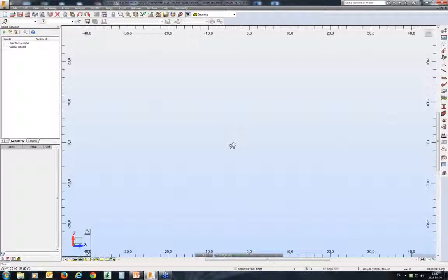Is there a method for fixing torsional stresses from the beam to the panel? Okay, there is a method. The surface elements that we have in Robot do not transfer torsion. So in this case, the solution is that you create either short dummy elements or rigid links between the nodes of the beam in which they connect the panel, and you connect these nodes with the neighboring elements. I mean the neighboring nodes, so nodes of the surface element generated in this area.